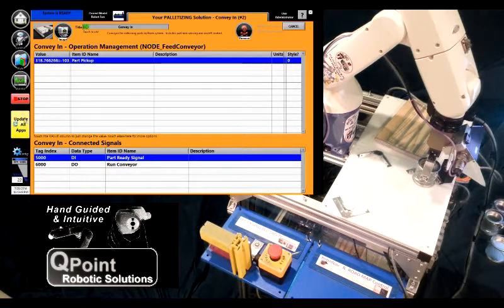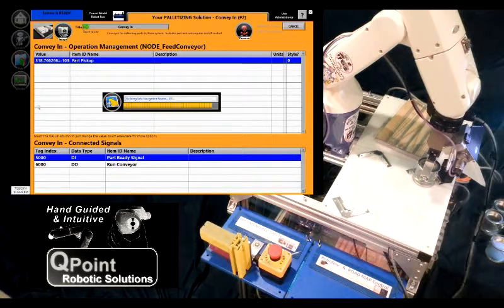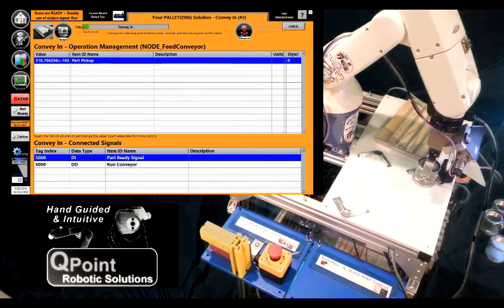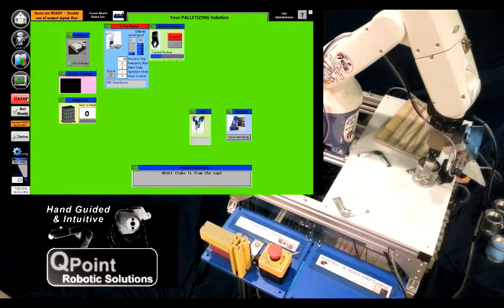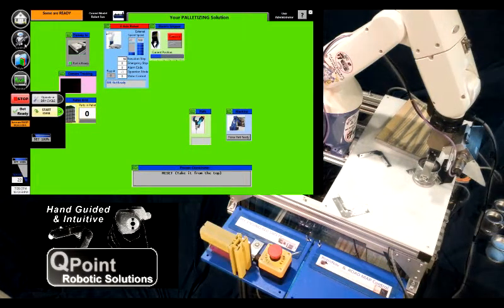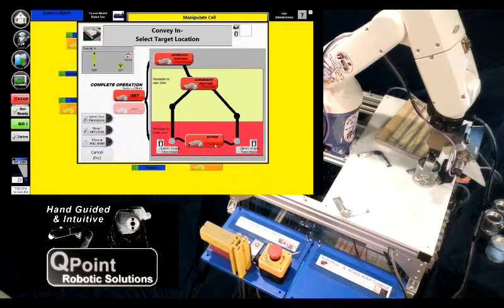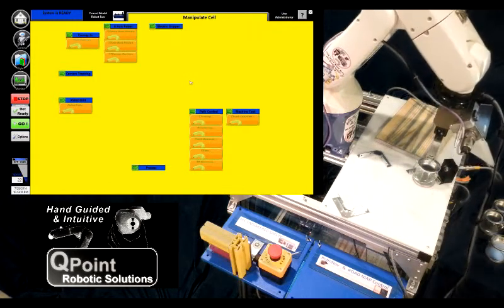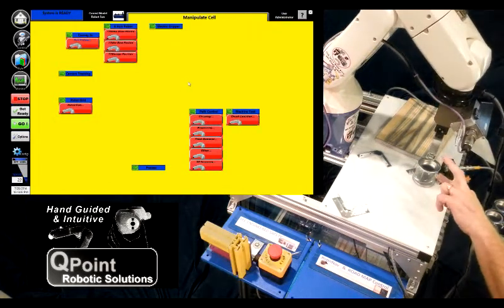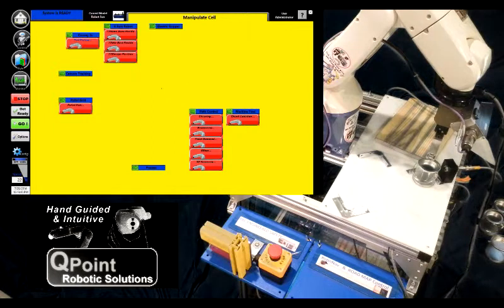And just as easy as that, now that we have it on there, we're able to go ahead out to the control side of things and just test. So we've enabled the system. On the control side, here's the part pickup. It already knows that I'm in the action position. If we wanted to say, hey, go to that clearance position, you can see it says it's 75 millimeters off. We set that as a vertical offset.